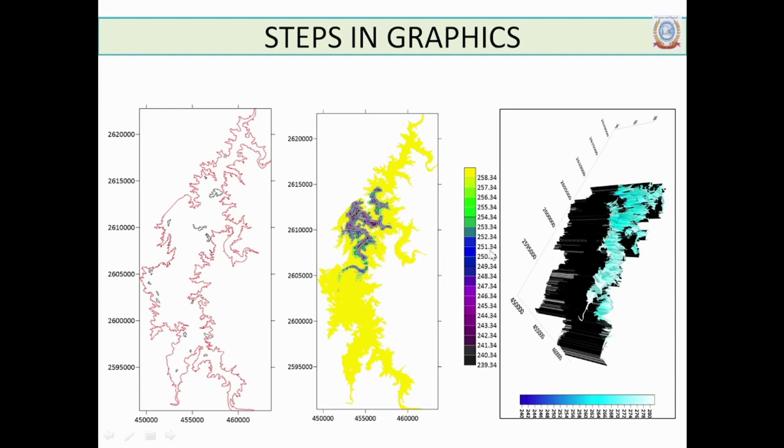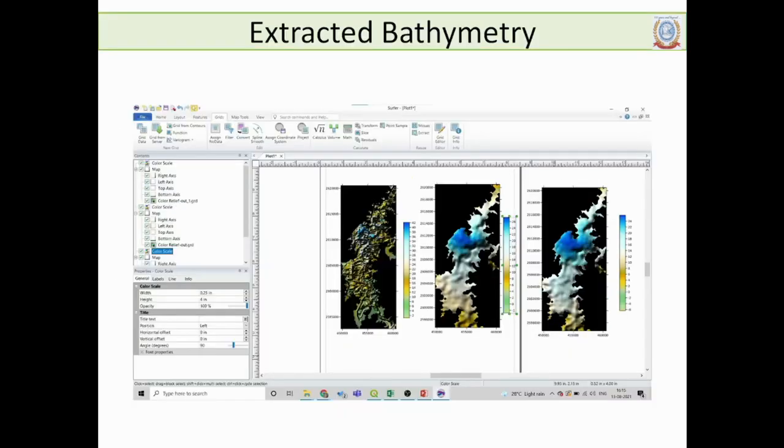This is a 3D plot of the same, where you can see the profile changes. Now here what we have shown you is, with the extracted bathymetry and with multi-band satellite data, we could produce the bathymetry even without surveying it. You teach the network with some percentage of data, and you can produce the output like this. Now let us see how the process, whatever data I have shown here, is actually carried out in the software using Google Colab, QGIS, and Surfer.